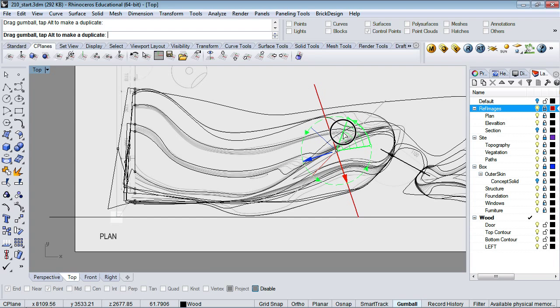So for right now, what I'm going to do is rotate it this way because I really want to focus on this transition area between the two of them, where we go from 3 steps down to 2 steps. And I'm going to want to control that transition really accurately. My first control position would be up here where it's starting to make that transition, and then the next cross-sectional curve would be down here in this transition. So anytime I have some complex area where I really want to control how the geometry is changing in tight ways, you want to add detail. That means adding cross-sectional curves. Okay?